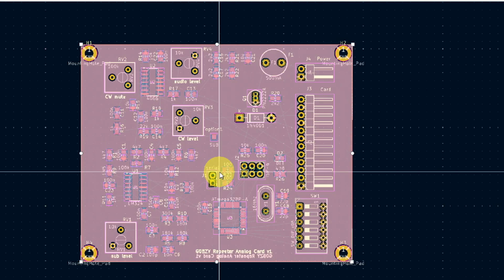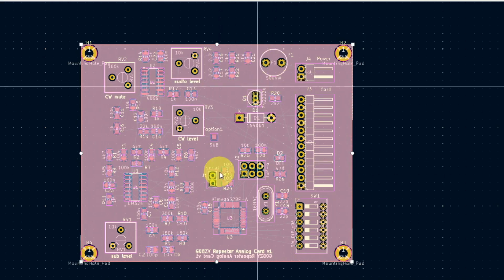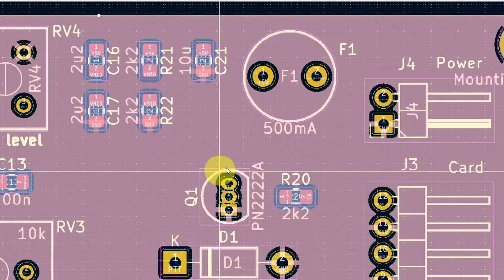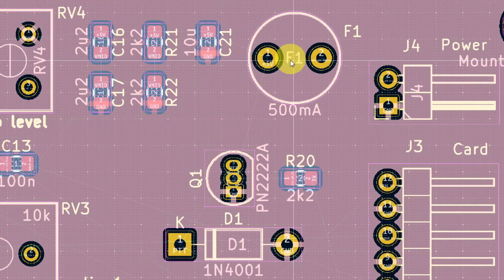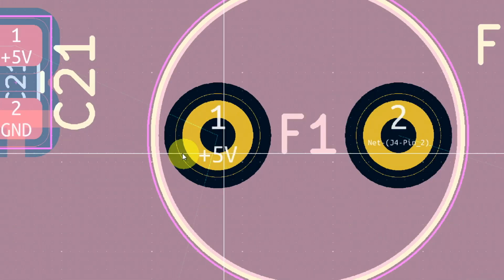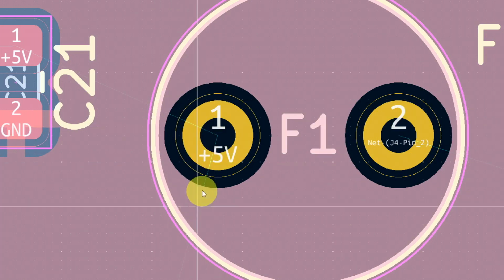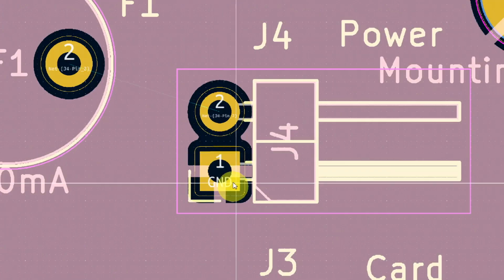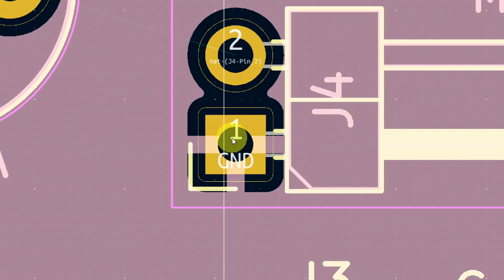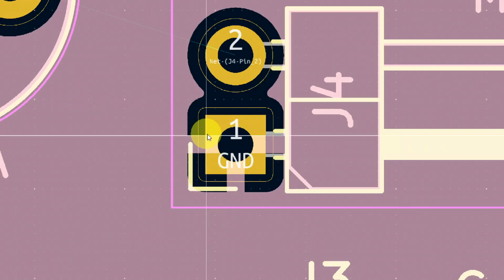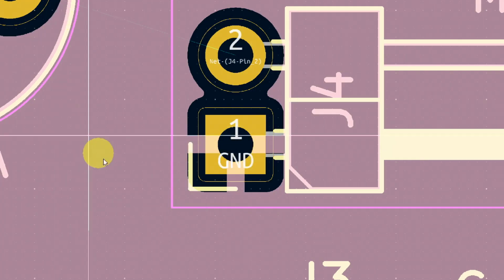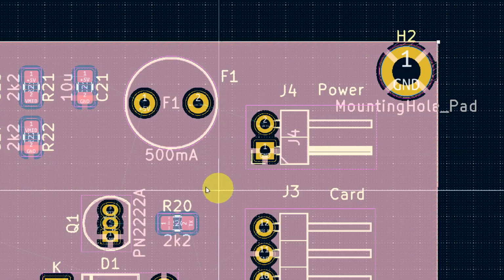We've now got a copper fill on the top layer and on the bottom layer, but we don't have any traces yet because we haven't run the Autorouter or made any manual traces. But you can still see the rat lines. Okay, they're quite faint. I don't know if you can see these, but we've got our rat lines here. But we've now got copper fills, and what it means is things like ground. You'll notice here's a ground pin on our power connector here. It is already connecting them to the copper fill. We've got rid of the ground traces, so the Autorouter has less to do.